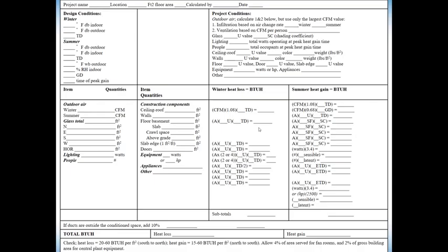Summertime it's so humid, we all know that, so we have to keep the humidity at around 50%. So 50%, again the authority's recommendation. So indoor relative humidity of 50% is going to be nice. By using all these values and the psychrometric charts, we are going to calculate our grain difference, and we are going to use all these in our calculations.